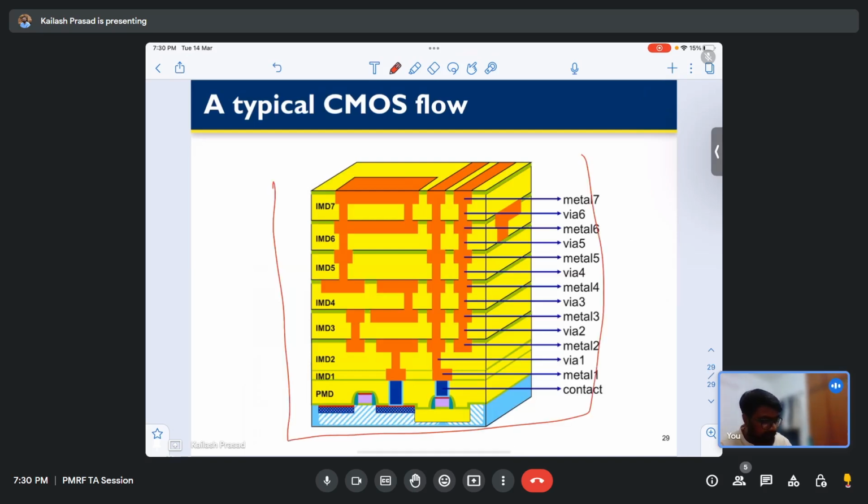look like this. Okay, I'm just showing you two transistors over here, but if you want to connect any of the gate of the transistor, you can see so many metal lines going on, right? What we study is only this particular part. Okay, but you should understand that to define the characteristics of whatever chip you are designing, along with this transistor, which is an extremely important thing, these interconnects are also important, because if interconnects are not fast, if they are not carrying information correctly, then the overall chip slows down.